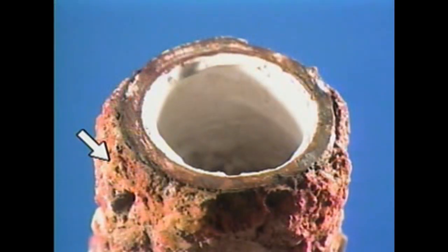If large amounts of solids are dissolved in water, the water may become highly alkaline. Highly alkaline water can cause corrosion, which is a chemical attack on metal surfaces. Other problems associated with dissolved solids occur when the dissolved solids come out of solution and form scale or sludge.